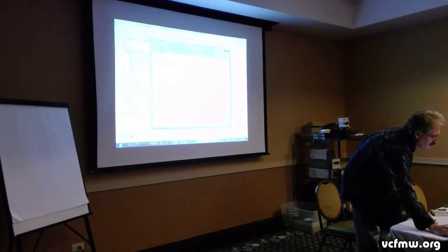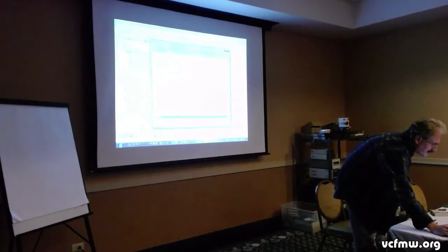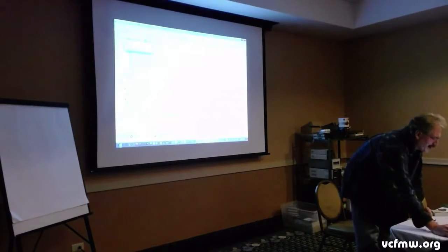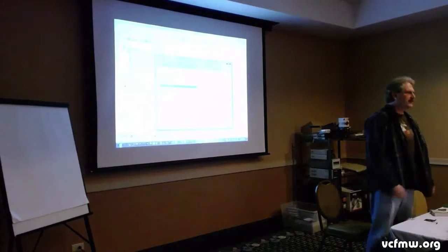So what you want to do is just type in a name for your project, and right here, just say HDL, and then once you type in the name of your project, you can go to the next item. And then it'll bring up a unit here. This is where it starts out, and you can say new source, and you can create a piece of source code. And this is the magic right here, I put Verilog module, okay?